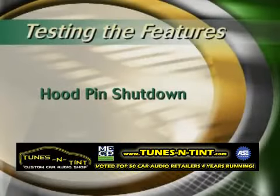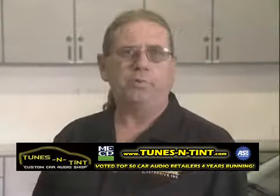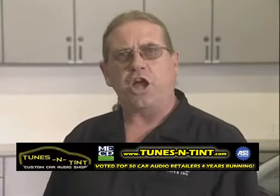Hood pin shutdown. With the vehicle in park, open the hood. Activate the remote start system. The vehicle should not start. If the engine engages, check your hood pin and connections. If the starter does not engage, your safety check is complete.